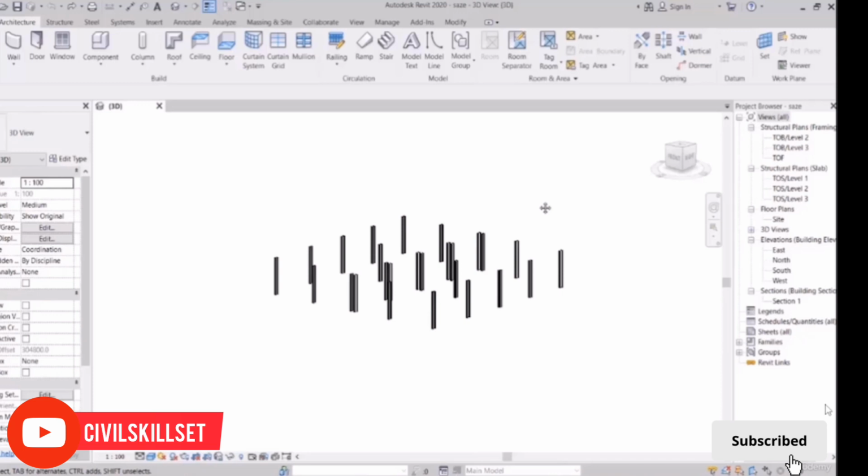But the second strategy, right, is to draw them floor by floor like walls. And then I said that there are many advantages for that. One of them is that we can have floor by floor dimensions, right? Well, this was really important in the walls, but here in columns, it's not that important because usually the entire skeleton is paid for. The floor does not matter. The next thing is about project managing, right? For example, in Navis, you can have a code that this is built floor by floor, but if you draw it flatly, right, suddenly, for example, all of the floors are built together.